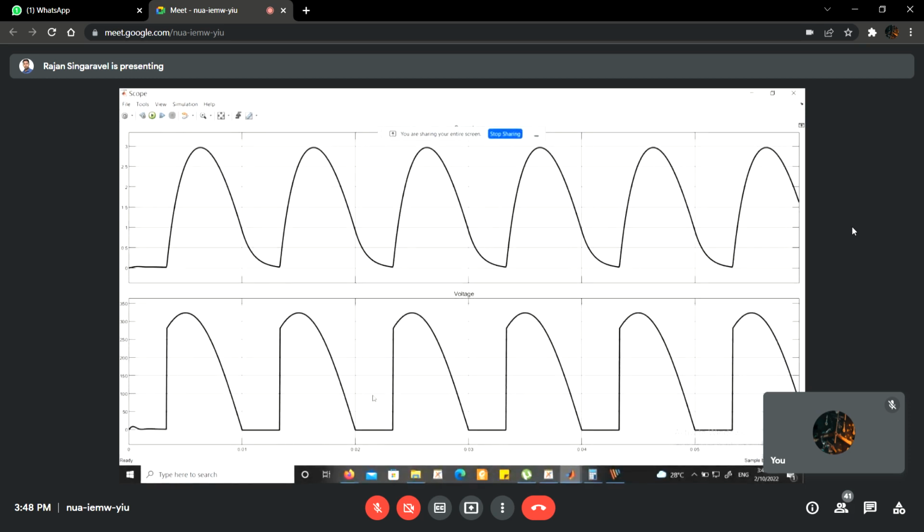In the previous case, if the current is positive, the same set of thyristors are conducting until the next alpha. But here, in the conducting pair, one is a thyristor and one is a diode. The diode is not working with respect to the current value. The diode is working with respect to the voltage across its terminals.